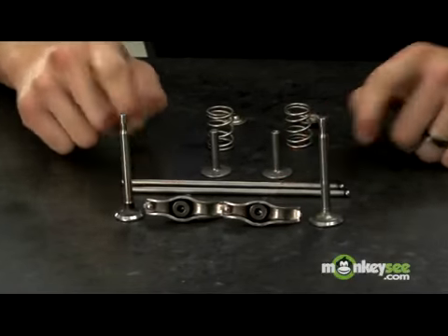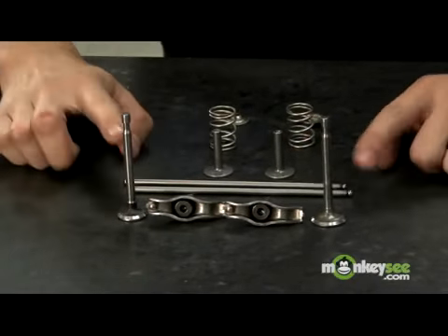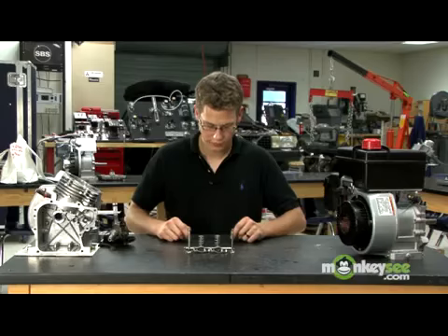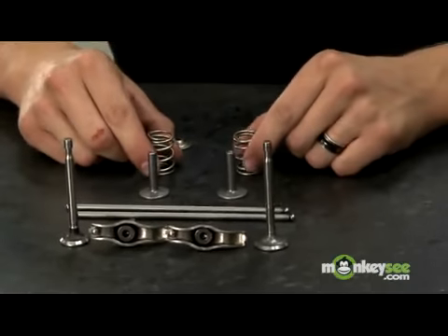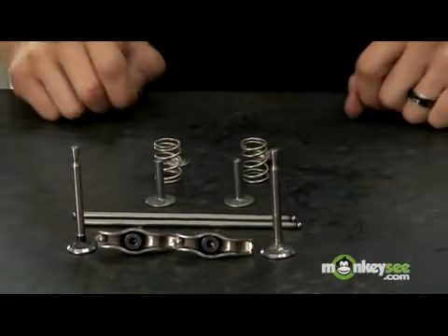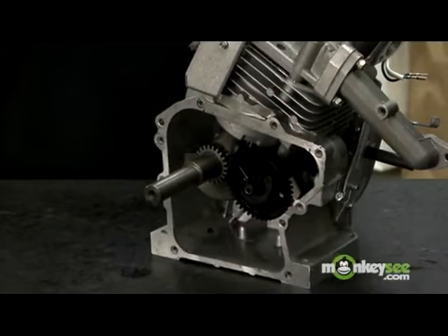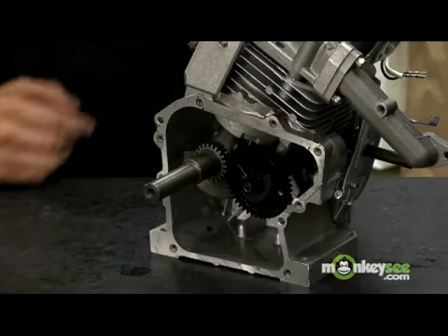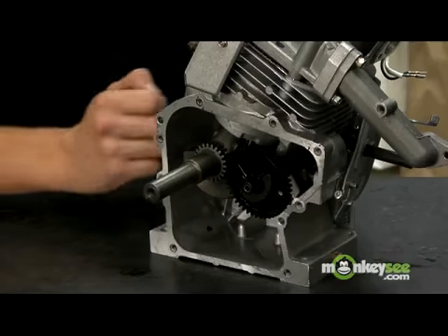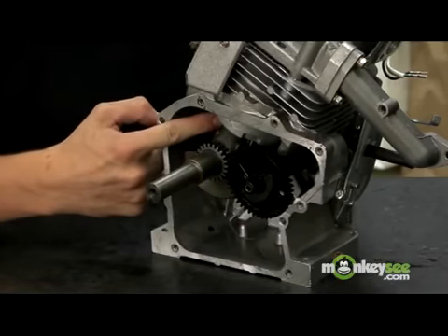We have rockers, much like in a car. We have lifters. We have corresponding hardware for the lifter system. We have valve springs and the valve spring caps. All of these components work together and can be better illustrated with my engine model. To illustrate all of the components in the mechanical system working together, I'm going to start with the engine's first cycle. The piston is situated in its topmost point.